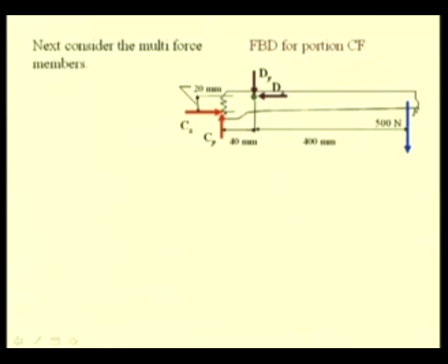This is clearly a multi-force member, and from this member for equilibrium we can write three equations, one moment equation and let us say two force summation equations. Let us take the moments of these forces about this point C. We take this point since we do not know these two forces Cx and Cy, but we have some relation between Dx and Dy from the earlier free body diagram.